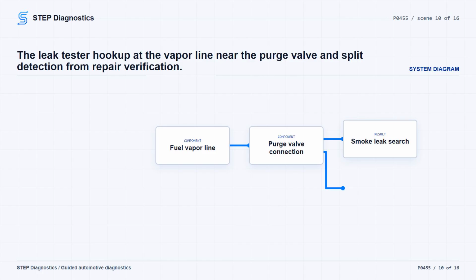With the ignition off, connect the EVAP leak detector with onboard nitrogen generator 218-522C or an equivalent unit. Disconnect the fuel vapor to EVAP canister line at the EVAP canister purge valve and connect a suitable hose adapter to that fuel vapor line connection.